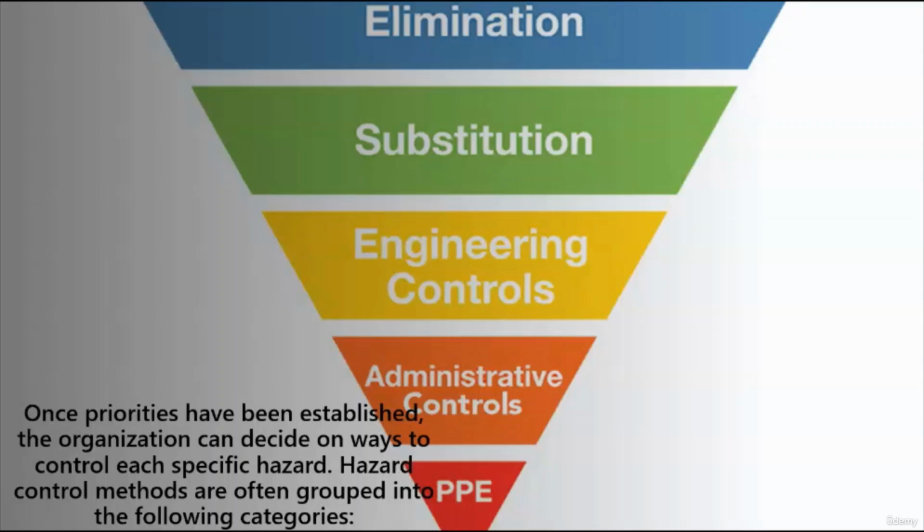Engineering controls typically include adopting processes to find a way to engineer the hazard away from the worker, typically putting some sort of blockade or control between the worker and the hazard. An example in terms of the chemical could be that if it is the fumes of the chemical that are harmful to the worker, we can decide to introduce ventilation into the environment, so that even though the chemical is still being used and it is releasing fumes, ventilators are put in place to ensure that the fumes do not accumulate and harm the worker. While this does not eliminate or substitute or totally remove the hazard, it at least puts a barrier between the worker and the hazard. And typically that is how engineering control works, especially in this example of a harmful chemical.